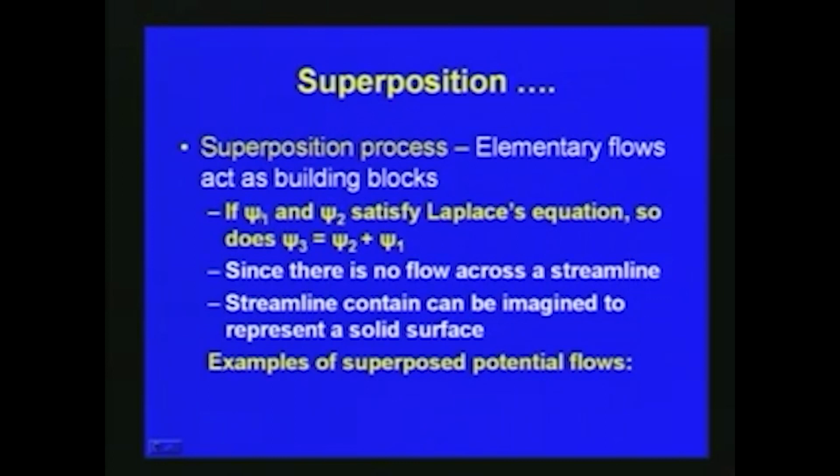For example, with respect to the Laplace equation, if psi 1 and psi 2, two stream functions, satisfy the Laplace equation, then when we add these stream functions psi 1 and psi 2, we get another stream function psi 3. This also should satisfy the Laplace equation.